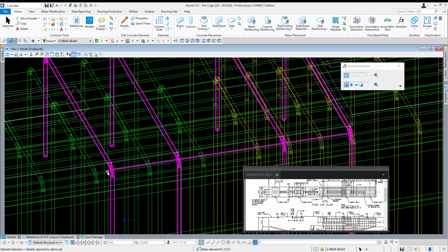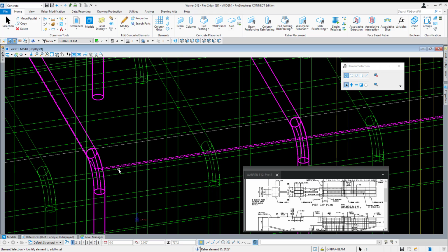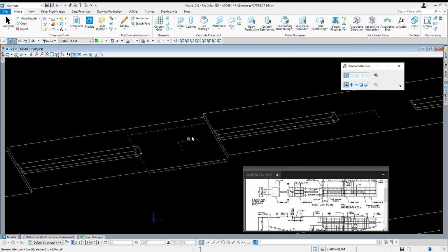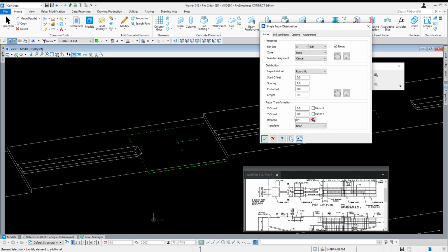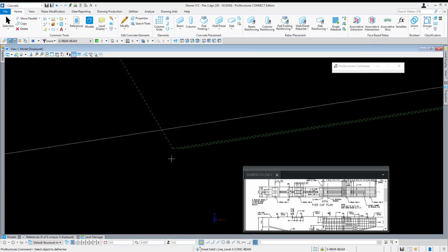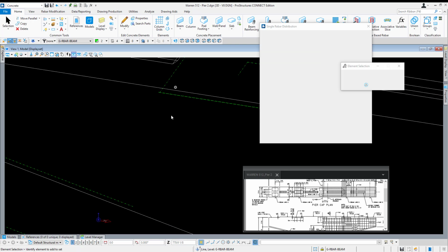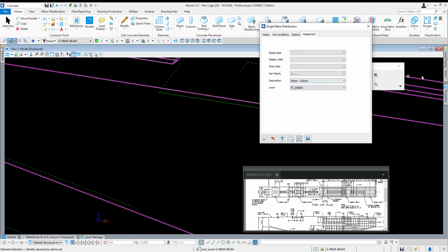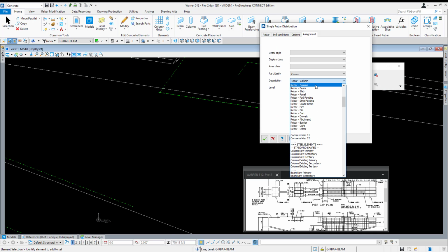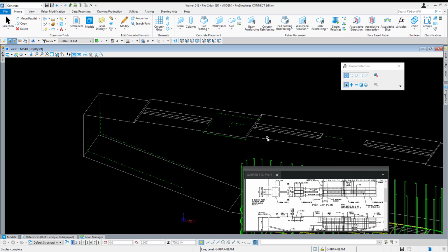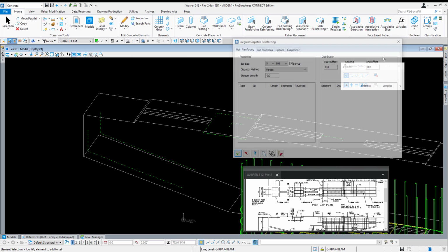So let me go ahead and turn my bars back off real quick, probably during that delete. Again, just single rebar distribution, phi is good. Okay, now in conditions, select concrete. Select bar guideline, which is the lower one. Just going to select bar guideline and select path guideline. And, oh, you know what? They got placed. Oh, they didn't, okay. Try that again. Select bar guideline, select path guideline.